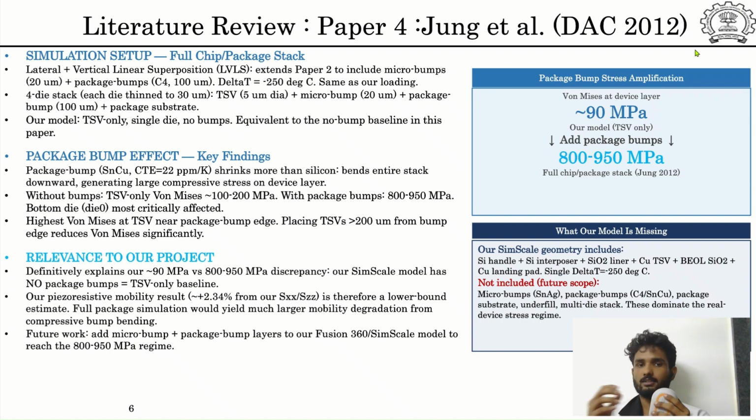Now coming to the right side box here, our model shows around 90 megapascal stress, but when package bumps are added, stress increases drastically to 800 to 950 megapascal. Now the model difference box, which is here. Our simulation includes only silicon dioxide, copper TSVs, and no package level component. It does not include microbumps, package bumps, substrate or underfill, which dominate real stress behavior.